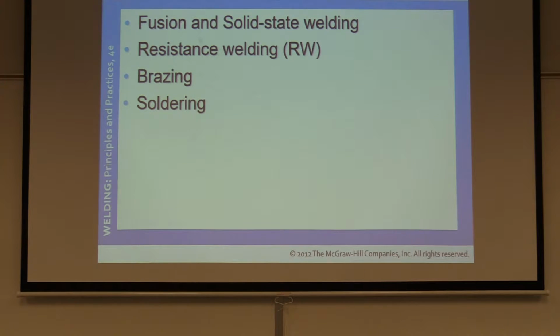Aircraft welders performing manual welding operations are required to have qualification certification. Again, you would not want a beginning welder welding on an aircraft that you're putting people's lives in, okay? You want to make sure that they're qualified, certified welders, keep the proper documentation. There's a lot of oversight and checks and balances that go within the quality assurance thread of welding as well. Okay?